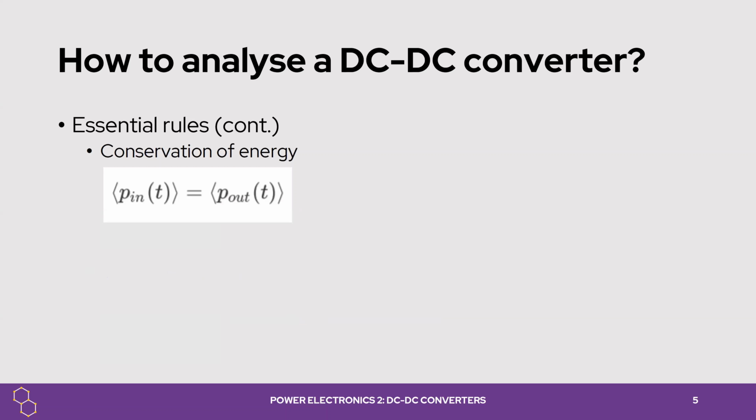In addition to all of these 4 rules, there is another helpful rule that can be used in PSS analysis. Consider a power conversion circuit which only uses switches, inductors, and capacitors. As a footnote again, these are the essential components of a power converter circuit. Therefore, we have mentioned the previous 4 rules. These components are all ideally lossless.